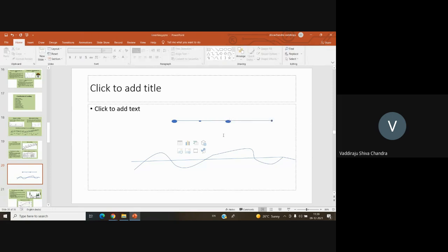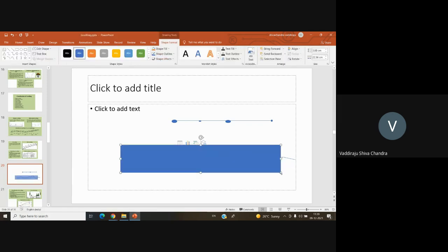So I'll be establishing a center line along this road. Suppose this is my road, and this is the width of the road which I want to lay. Okay, so along the center line of this stretch, I'll establish some points at every 10-meter or 20-meter interval, depending on the accuracy, the purpose of the project, as well as the cost of the project.